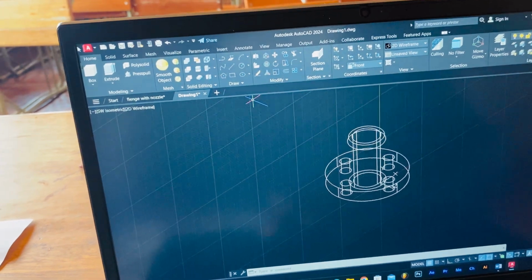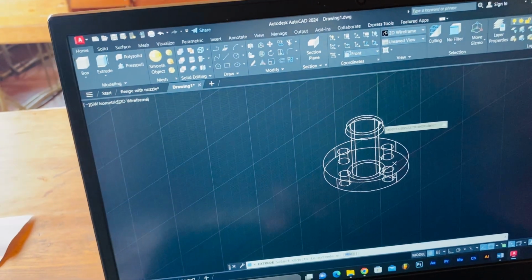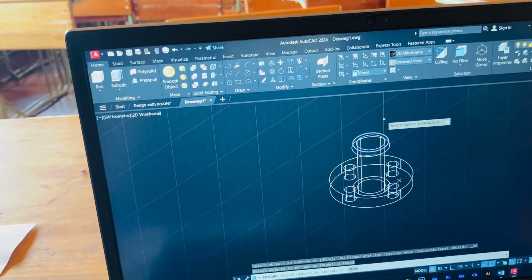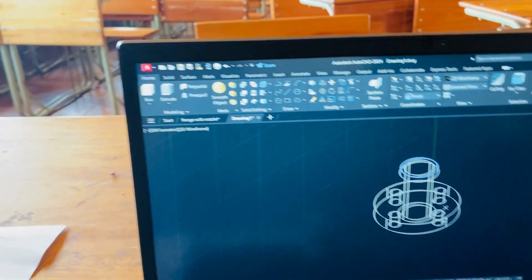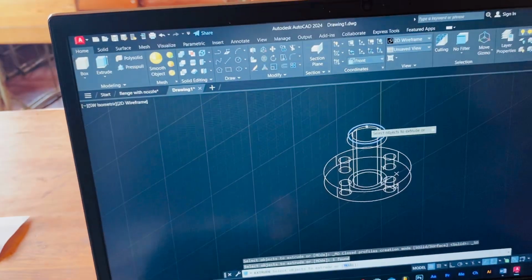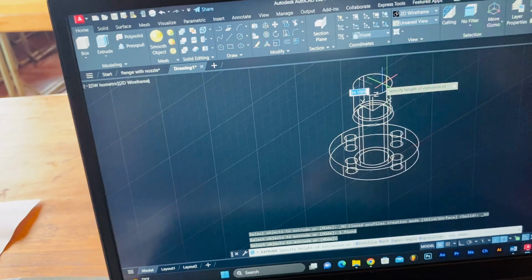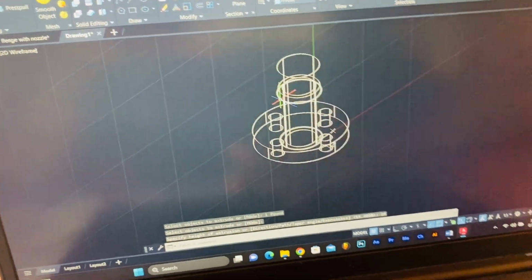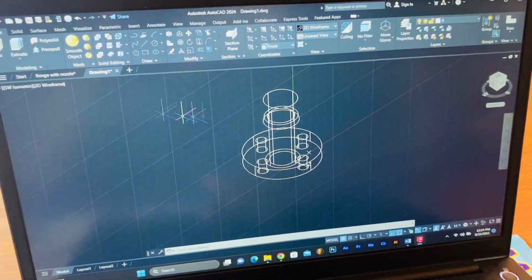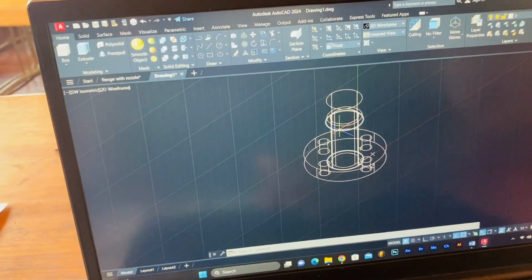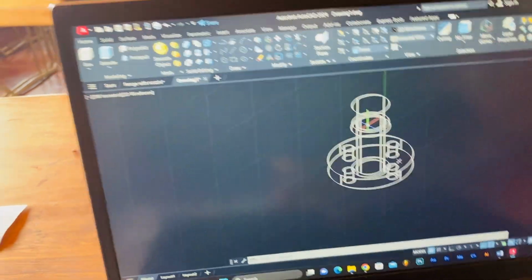Can I do that? Extrude this circle. How long is it going up? Let's check it. It's 24. When I extrude this one, I'll simply put 24. I have extruded it successfully, and then now I have to add another circle there.